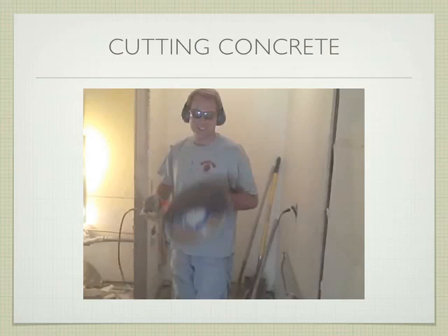You put in your rebar. You put in epoxy to reestablish the grid of rebar that's reinforcing that particular piece. Then you go ahead and put in a new moisture barrier. Basically, you reverse the whole process all the way up. You pour your slab, and then finally you can start with your new shower.